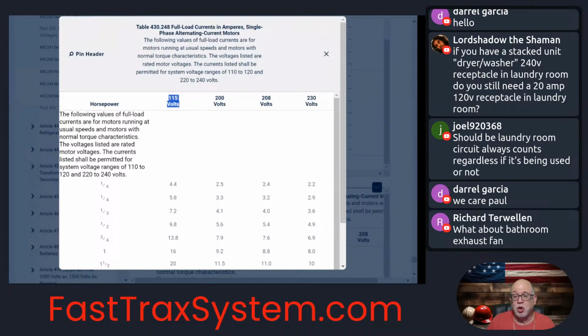Now don't get confused if it's for something like that dishwasher. If it had said 10 amps times 115, then you use the 115. You use whatever they give you. In our case, it was 120. But if you get a motor question and they give you 120 or they give you 115, you use what they give you. It's just that in our case, since the motor was 120, we know that most motors on the nameplate might say 120, but they're going to be rated at 115. So that's why we're using the 115 column, in case anybody got confused on that.